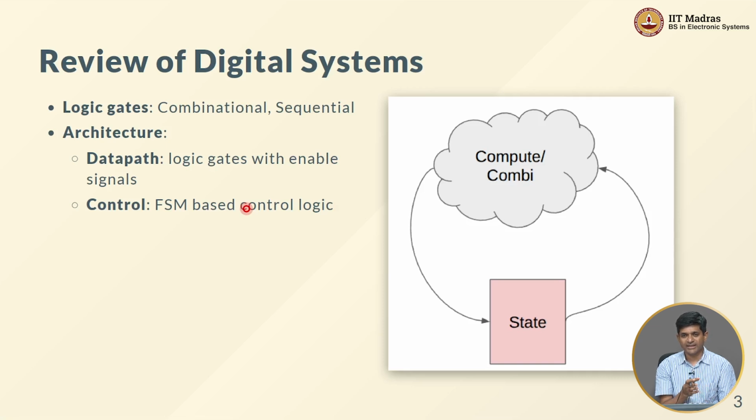What those select signals are doing is, for example, deciding that you have a choice of many different inputs that could go into an adder or a multiplier, and the select signal decides which of those actually goes in there. Similarly, I could have an ALU, an arithmetic and logic unit, and the select signal might be used to decide whether it is doing an addition or a subtraction or a multiplication or some other kind of operation, right.